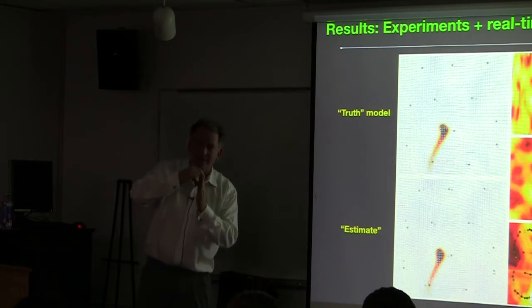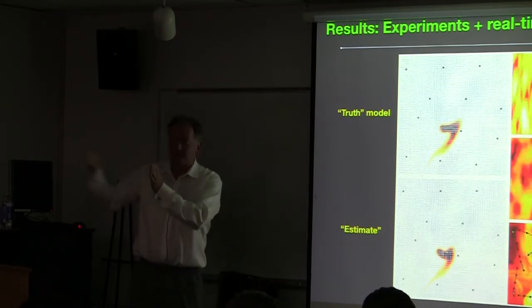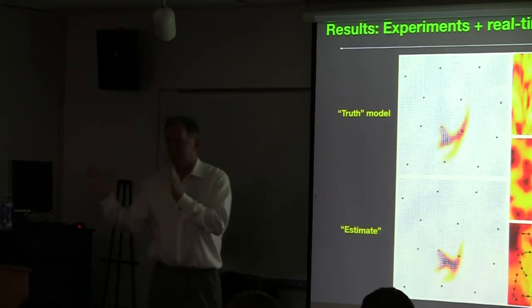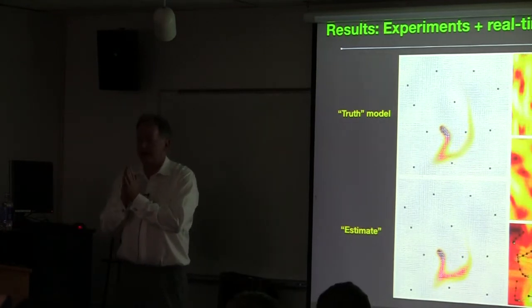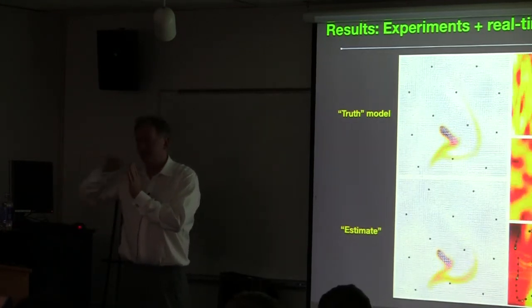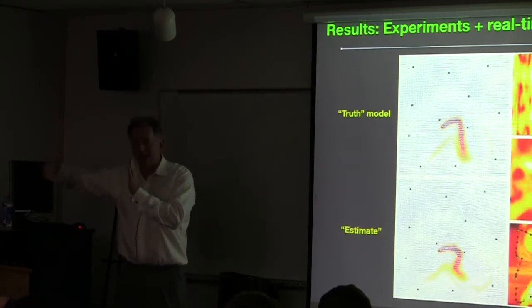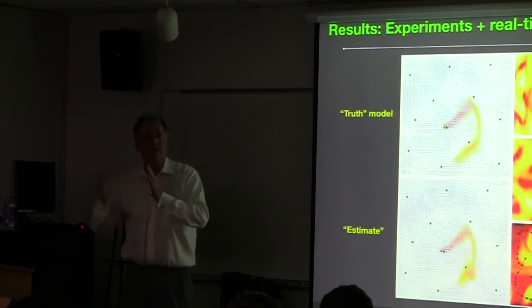So y itself does not come into your statement of your estimate of the state estimation error. So that means I can rigorously solve a problem looking into the near future and use a model predictive control type setting to minimize the trace of the covariance matrix at the forecast time by putting in feasible control inputs into the individual path of the